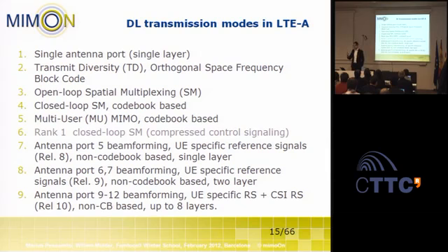There are reference signals that are specifically signaled for particular users, which are used to inform the users about the selection of these beamformers. I will speak about this later on. This concept of user-specific reference signals and non-codebook based beamformer design was further enhanced in mode 8, where up to 2 code words could simultaneously be transmitted, or 2 layers could be transmitted. And in LTE-Advanced, up to 8 layers can be simultaneously transmitted on the same time and frequency resource. I will show you in detail what that means.